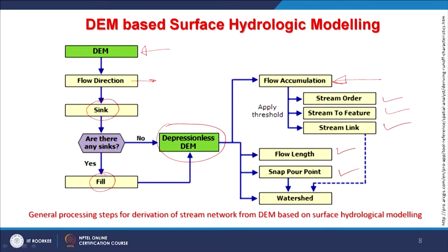The only problem you will face is in the boundary areas, because as I said in the early discussion, one watershed ends and another starts. When you have a boundary or margin of a digital elevation model, you do not get the watershed in the adjacent area. So only that part will have a limitation, not really an error but a limitation.